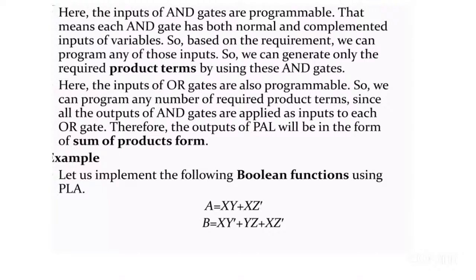Here, the inputs of OR gates are also programmable. So we can program any number of required product terms, since all the outputs of AND gates are applied as inputs to each OR gate. Therefore, the output of PLA will be in the form of sum of products form.